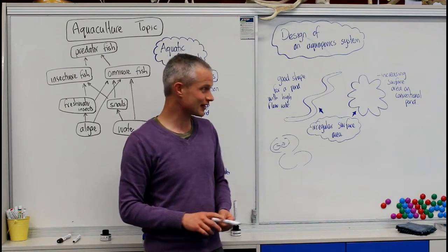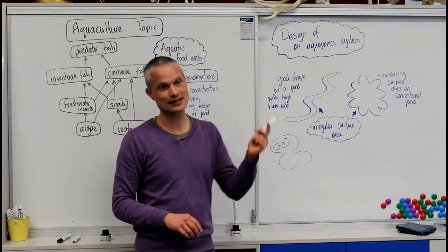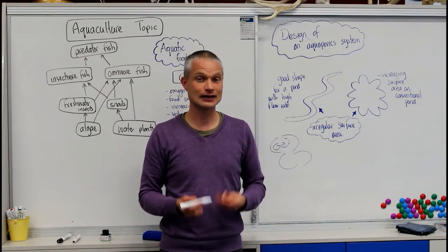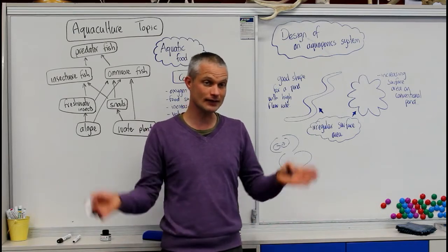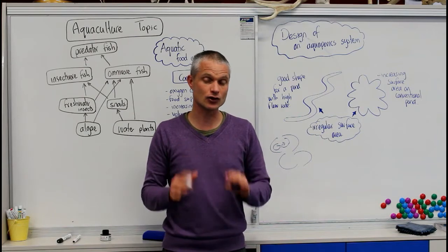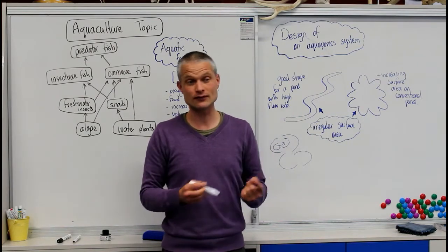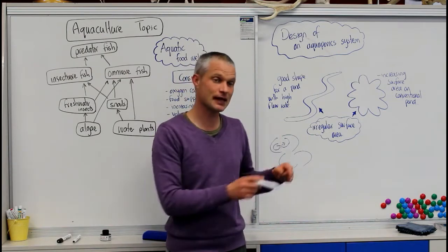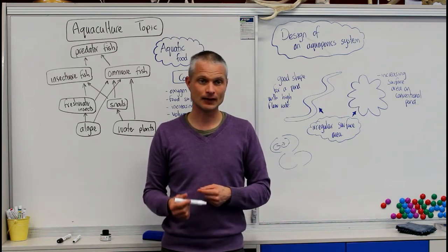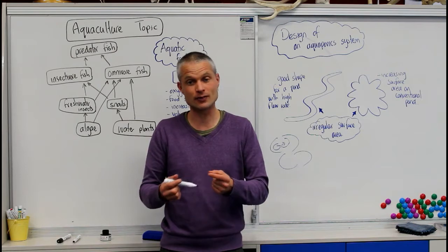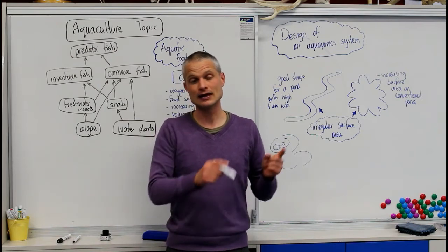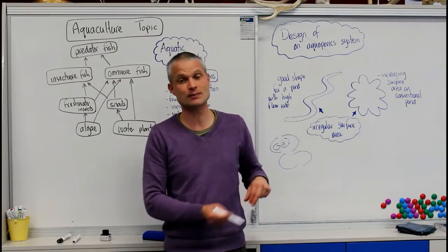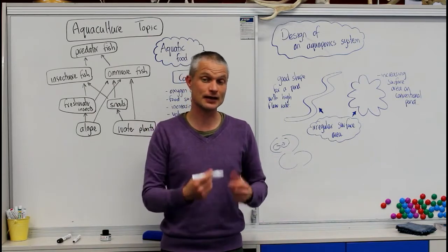So the flow form, I'm remembering its name now, so as it goes through the flow form and gets oxygenated, it can then go through a gravel reed bed, and the bacteria and the reeds in that reed bed will help clean the water before it goes back into the pond again. And then by planting out the pond, you can help keep that pond cool and the temperatures as low as possible. Or alternatively, if there's availability of a local stream or a pond that you can pump from, it can go through your system and then back into that waterway again, as long as there's some level of purification of the water before it goes back into that natural water body again. So after leaving your aquaculture system, if it goes through a wetland system, that will help take out any excess nutrients before it goes back into that natural habitat again, so that it doesn't contaminate that natural habitat.